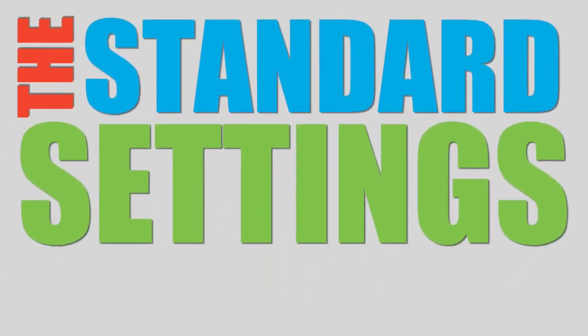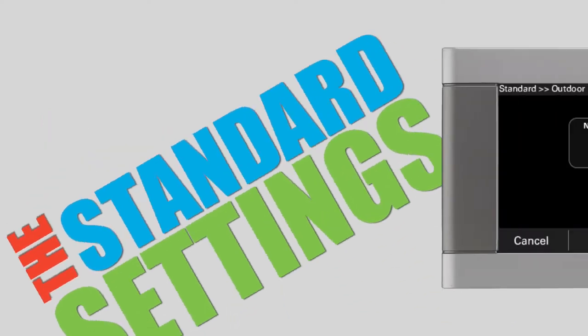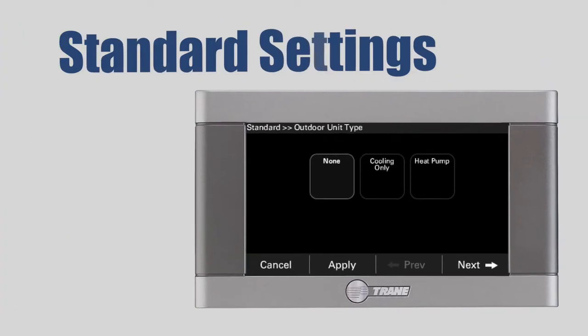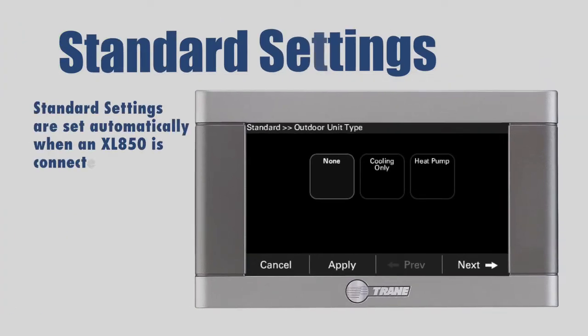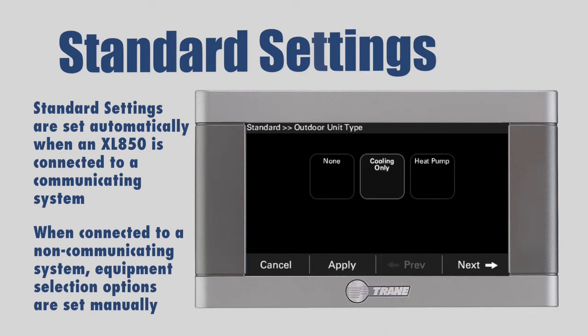Standard Settings. An XL850 control installed on a communicating system will auto-discover all communicating devices. Therefore, standard settings will not require setup. If an XL850 or XL824 control is installed with non-communicating equipment, standard settings will require the manual selection of the appropriate equipment. Select your outdoor unit type. For this demonstration, we will select Cooling Only from the outdoor unit type and press Next.